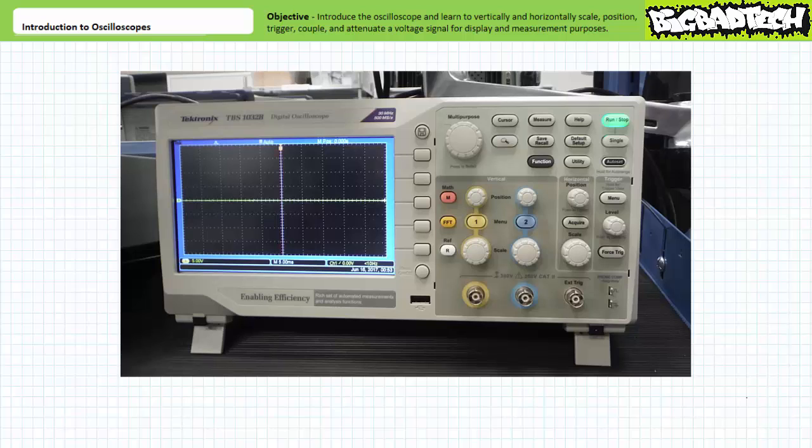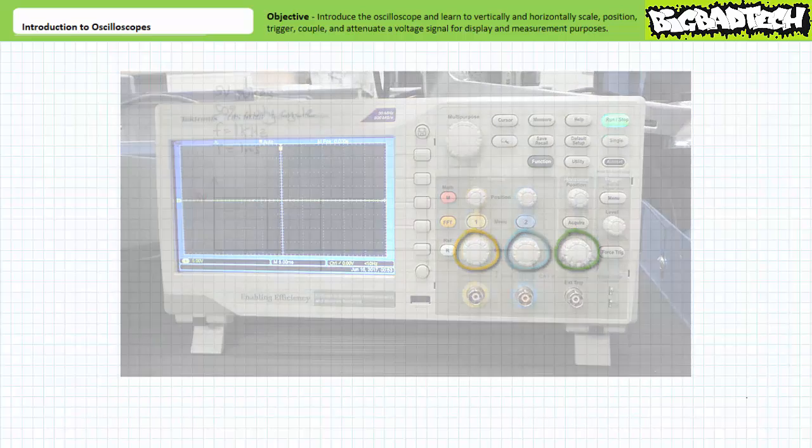In summary, an oscope consists of a screen with volts on the vertical y-axis and time on the horizontal x-axis. Elements within the vertical group are used to adjust volts per division for each channel, and the horizontal group is used to adjust seconds per division for both channels. The triggering group and the function buttons... You are now hereby authorized to touch only the vertical scaling knob for channel 1, the vertical scaling knob for channel 2, the horizontal scaling knob, and nothing else.